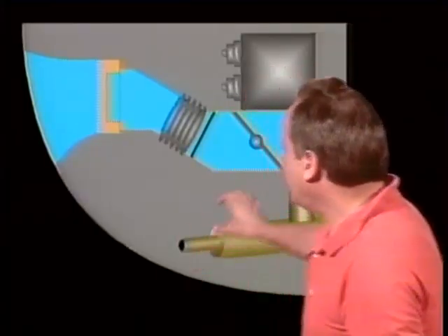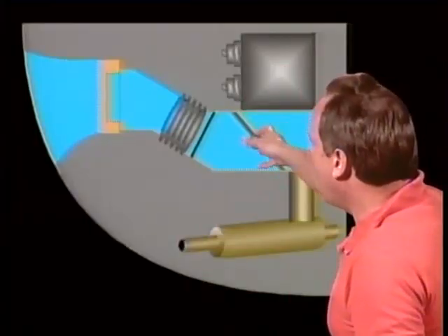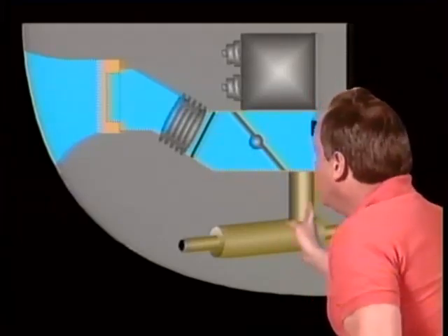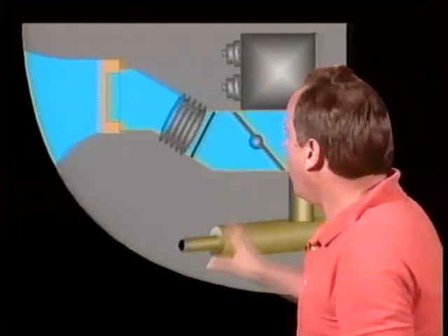And they're going to say, all right, let's assume that a pilot comes and says, oh, look, I'm not getting full power on takeoff. What could be one of the problems? And the answer is the linkage here in the carburetor heat valve, this butterfly valve, could be allowing carburetor heat to be heating the intake of the engine on takeoff.